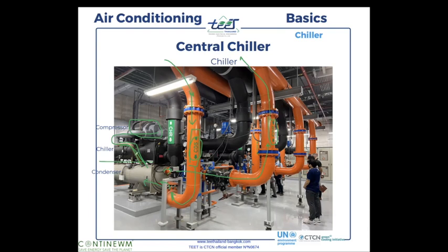You have the refrigerant fluid, we cool it down with the water from the cooling tower, and somewhere, it's difficult to see, the refrigerant fluid is inside, going through the coil, getting cooled by the water from the cooling tower, and getting inside this part, which is the chiller.